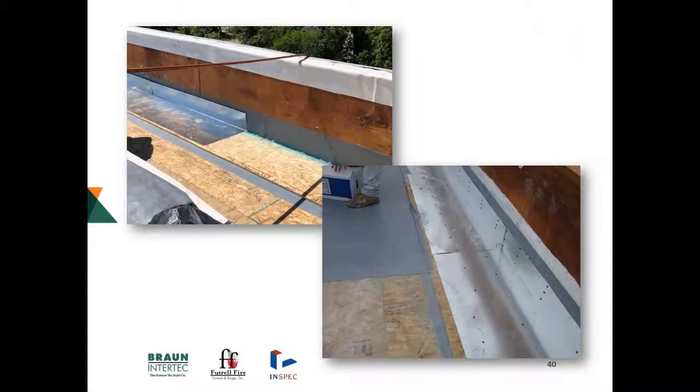This photo on the top left shows the vapor retarder, the gray material, and it shows it coming vertically and then a little bit of it sticking out beyond that plywood. Well, that's all one continuous piece that tied to the metal Z-girt, or Z channel, I should say, that was below. And then you're seeing the plywood in that upper left, and it's metal on top. That's the reinforcing plywood and metal to strengthen that parapet. That leading edge then of gray vapor retarder material, as shown on the bottom right, is where we tied into the main roof vapor retarder for the project.